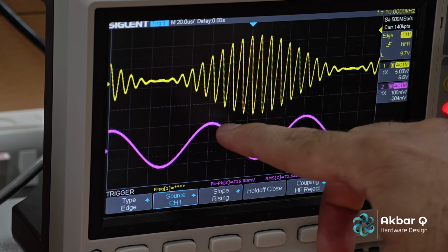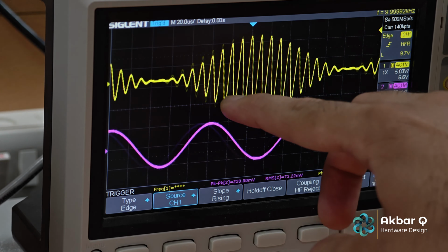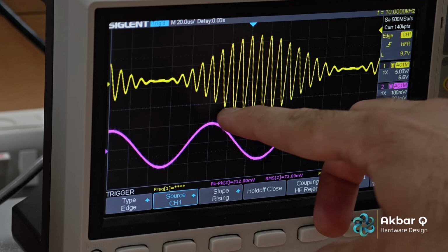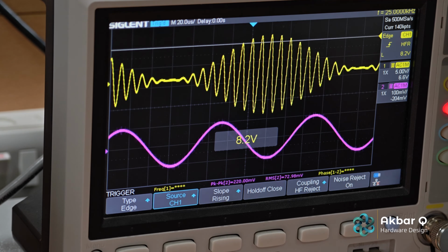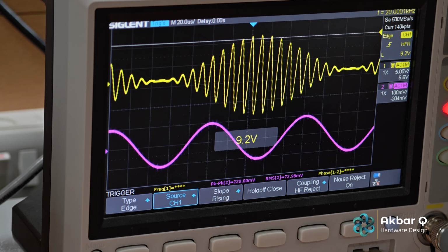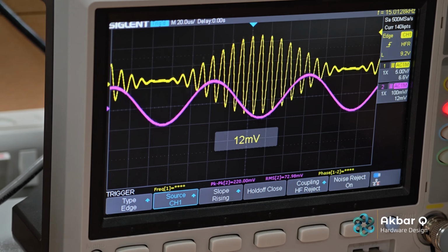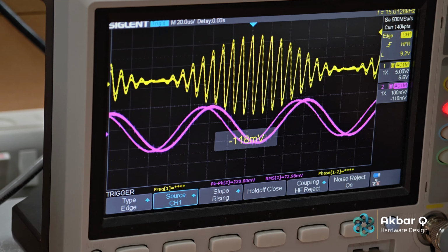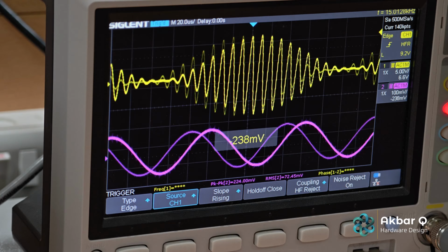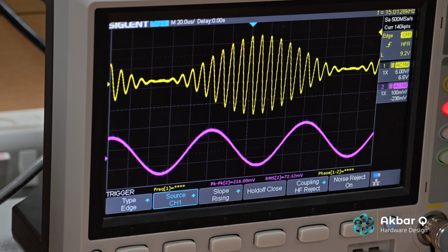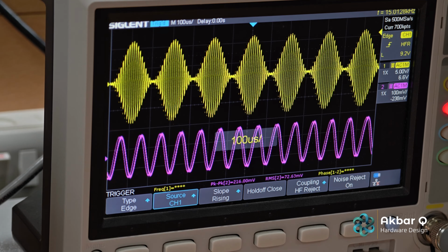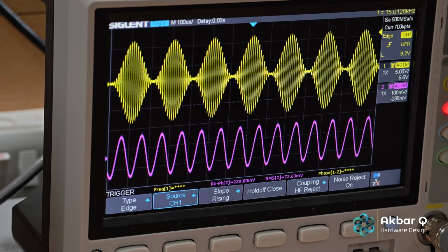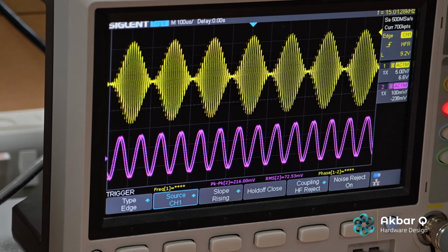If you observe, this sine wave represents the change in the voltage as well. When the sine wave is on the lower end, it is lower on the modulated signal as well. Move it closer, you can see that. Again, the top is the modulated signal and the bottom is the demodulated signal. The modulated signal has amplitude variation while the data signal is causing that modulation.